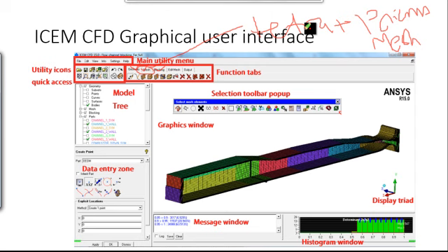During the creation of tetra prism mesh, you may also get the pyramid mesh, where the prism mesh is not possible. So in the mesh menu, you are dealing with any other mesh type other than the hexa mesh. While in the blocking, ICEM CFD has combined all the functions related to the hexa mesh inside the blocking.